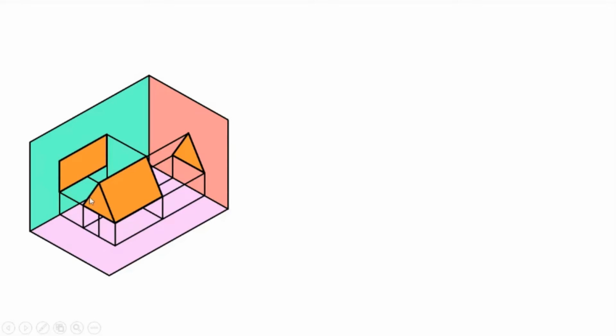So this will be the case. The axis will be from this point to somewhere here. In that case, the axis is parallel to both HP as well as VP. The true shape of the base, the triangle, will be visible only in the side view. That is why we need the side view in this case. Without the side view, we will not be able to obtain the height of this particular rectangle.